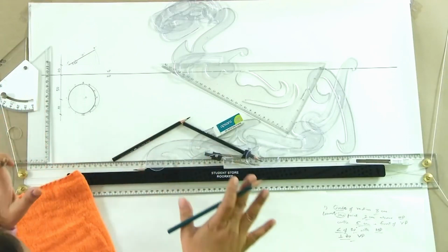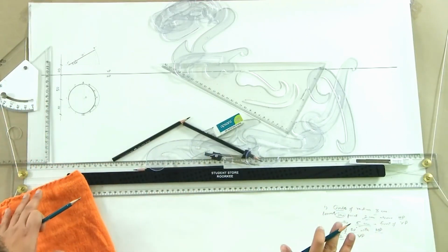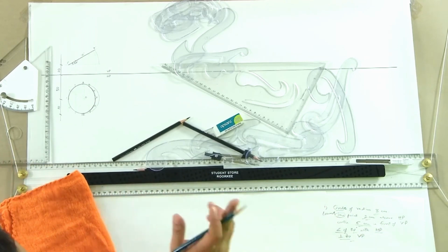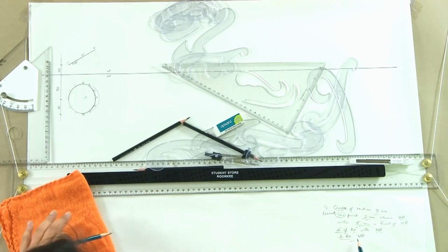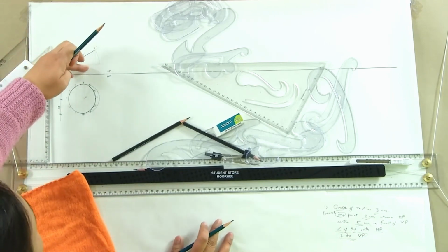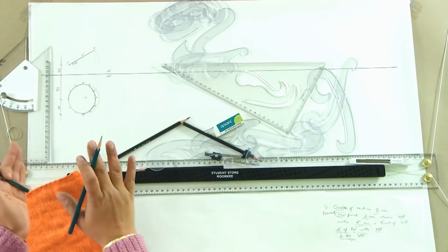These are the steps. You will start by assuming that the plane is parallel to one of the reference planes and then gradually inclining it. To start with, you should keep the plane to which it is perpendicular the same. In this case, it was perpendicular to VP. We took it as that and then we inclined it with HP.